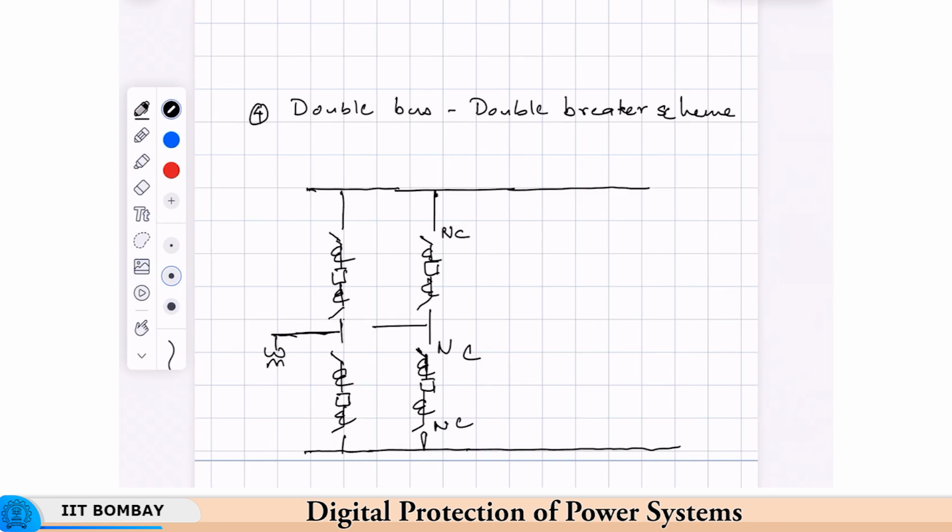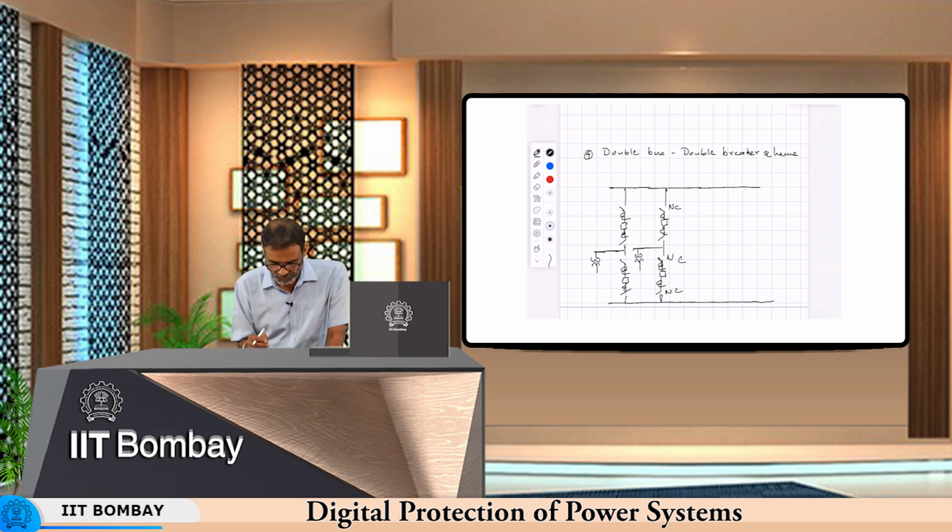Though there will be voltage transformers provided on the bus, here we can't keep the line charged for a longer time if the distance protection operates in zone 2. So, we will need some pilot communication. For that reason the line VTs will also be required.